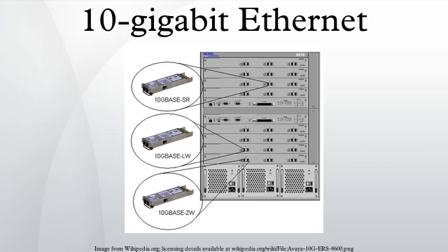Copper. 10G Ethernet can also run over twin-axial cabling, twisted pair cabling, and backplanes. 10GBASE-CX4 was the first 10G copper standard published by 802.3. It uses the XAUI 4-lane PCS and copper cabling similar to that used by InfiniBand technology. It is specified to work up to a distance of 15 m. Each lane carries 3.125 Gbaud of signaling bandwidth.